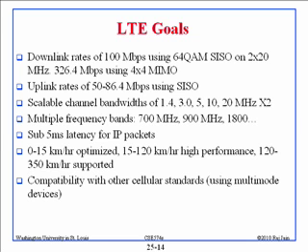The WiMAX frame is 5 millisecond long. They repeat every 5 millisecond, downlink, uplink, downlink, uplink, downlink, uplink, right? So first you have to find an uplink to tell the base station, which is 5 millisecond, and the base station tells you that, okay, you got the slot number 3, then you send the data, so there are already 3 trips, right? 15 milliseconds before the data made it there, right? That's too long.